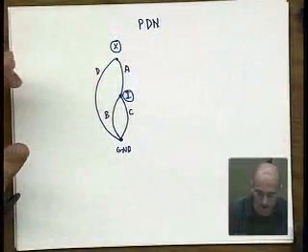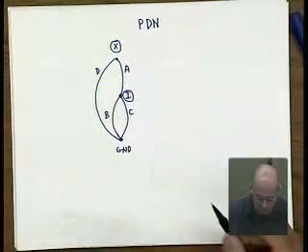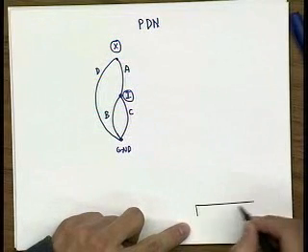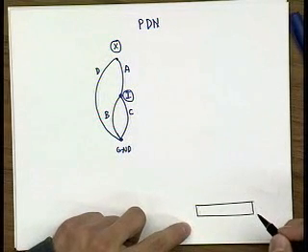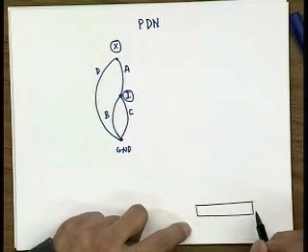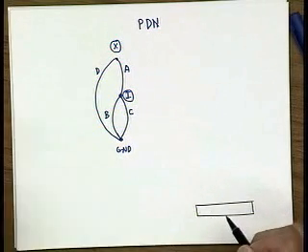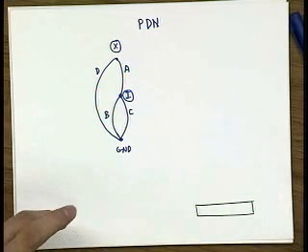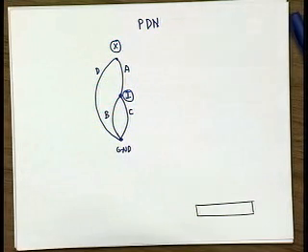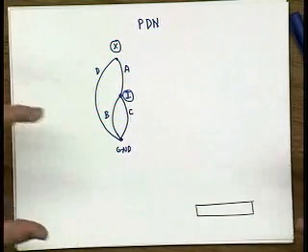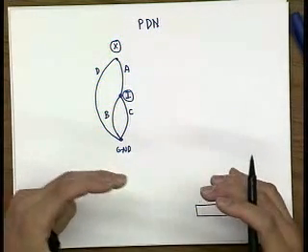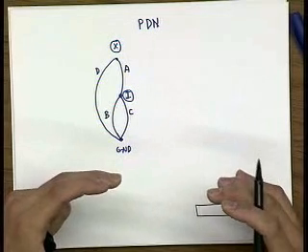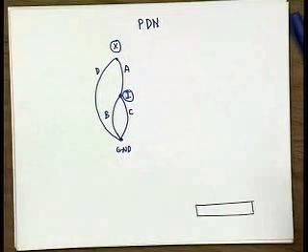If you decide, for example, to have a horizontal MOS transistor, and then you have to implement a couple of these NMOS transistors in this manner, you can only grow horizontally. You can't use the vertical dimension. So if you're able to arrange these signals in a way that you can have all of these diffusions shared, that reduces the width of your standard cell and increases your layout density.